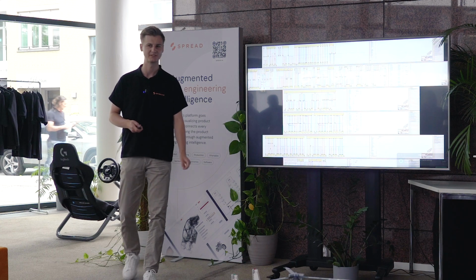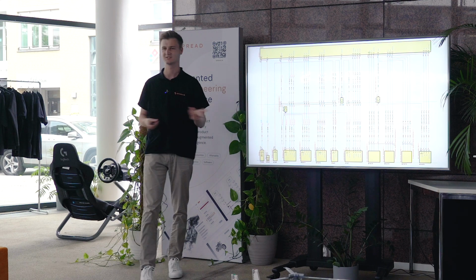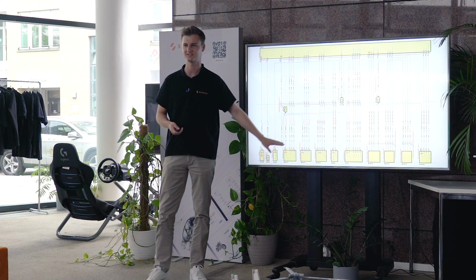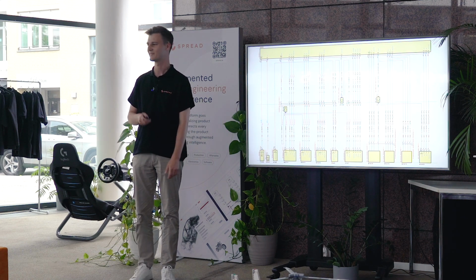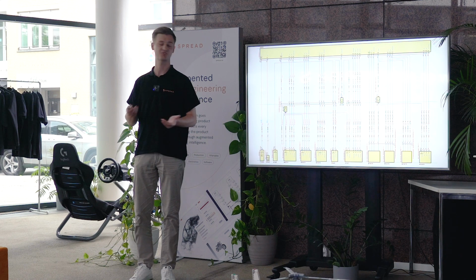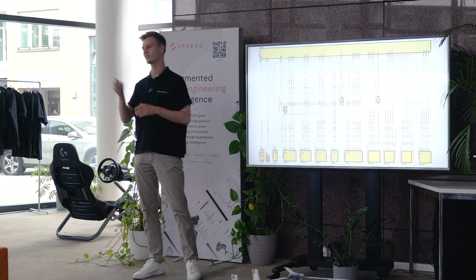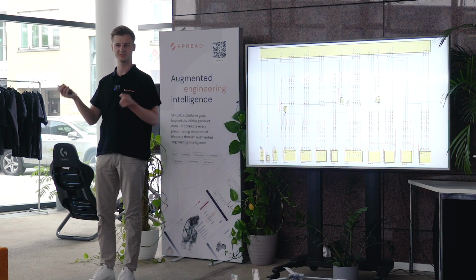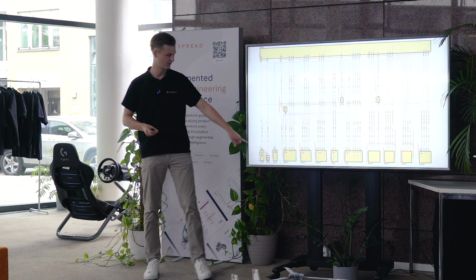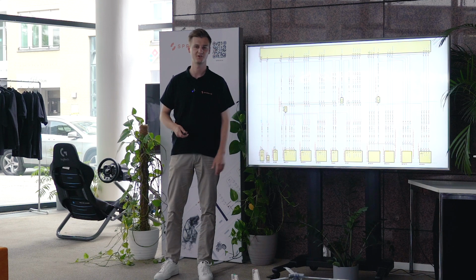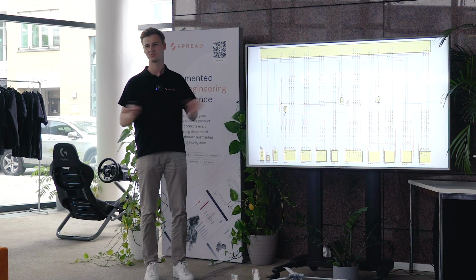We want to zoom in on one specific case. It's the control unit for the right seat. So it is connected to various motors, sensors, actuators, and you can just get a feeling of the complexity. What often happens is that the actual root cause is not even in here. Robert just showed us that a signal from 2 software modules can go through various wires. So it does not have to be included in here, but maybe from a component to a different one. So if we open a second component and cannot find it here, there opens just another tree of options.